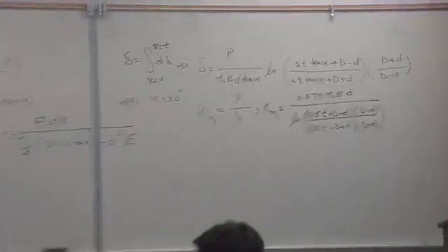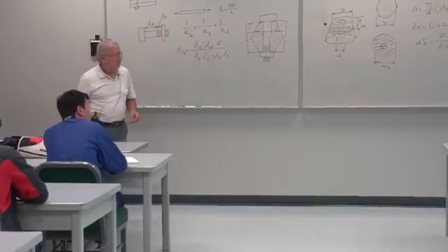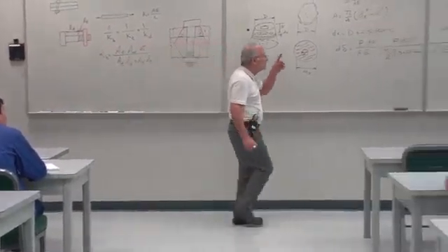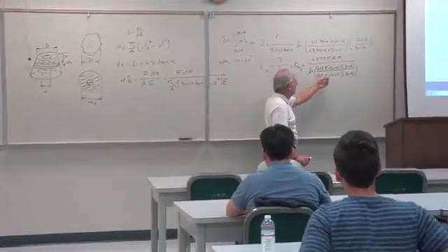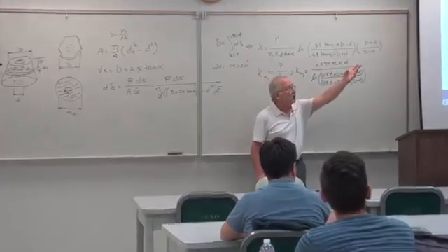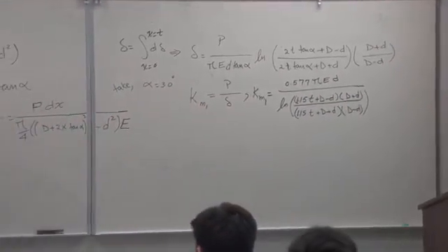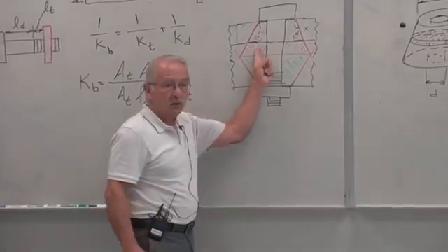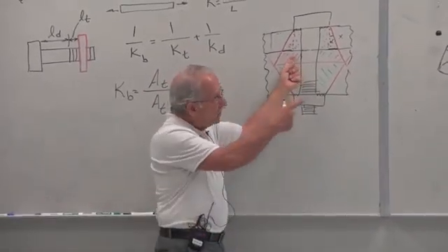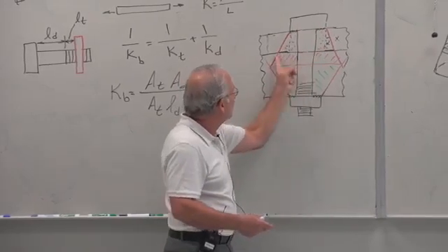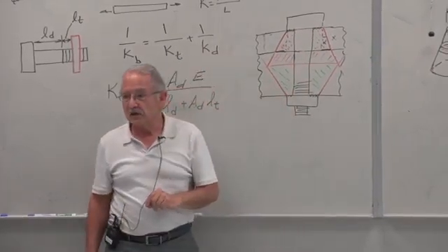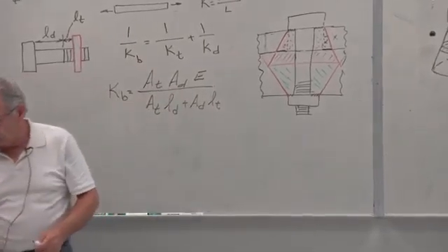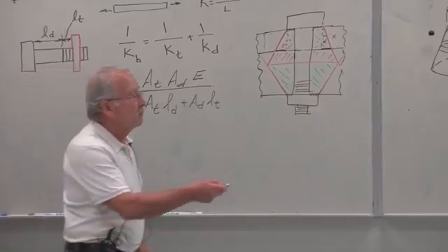One very, very important point in the use of this equation. This D, the capital D, in this case is equal to the bolt head diameter. But if you are looking at a frustum in the middle of the pack, this one for example, you have to remember that that D is no longer this. It's that distance. Does that make sense? Because everything is based on the small diameter, and you go from that with the distance x.